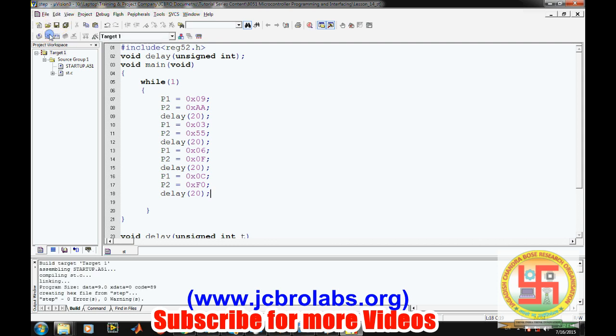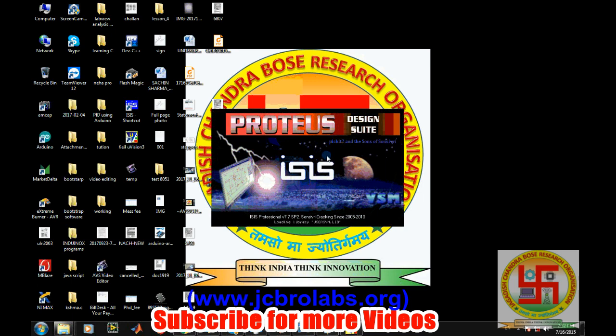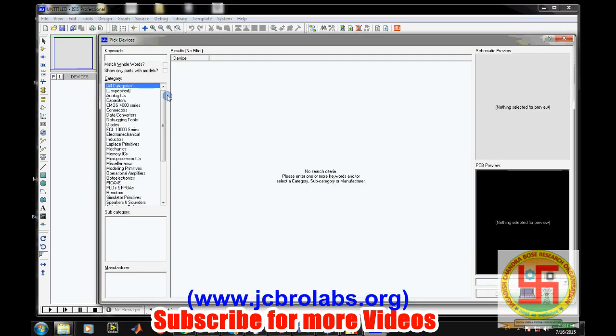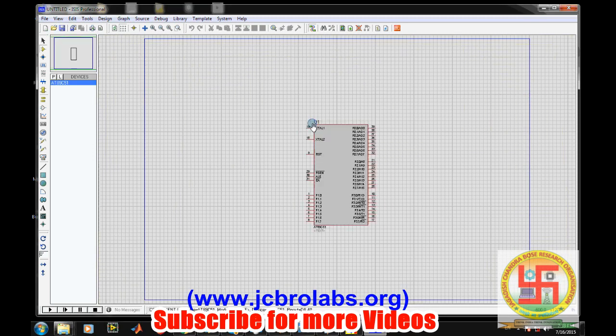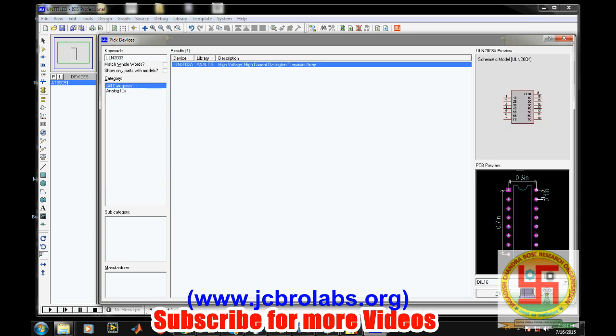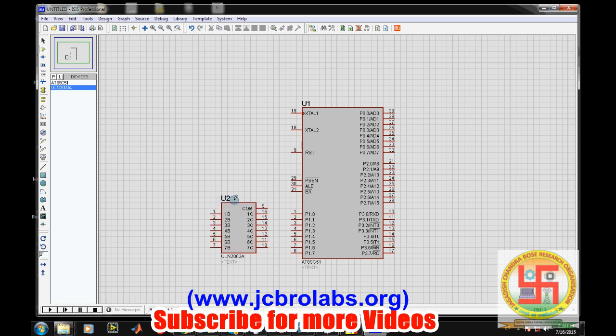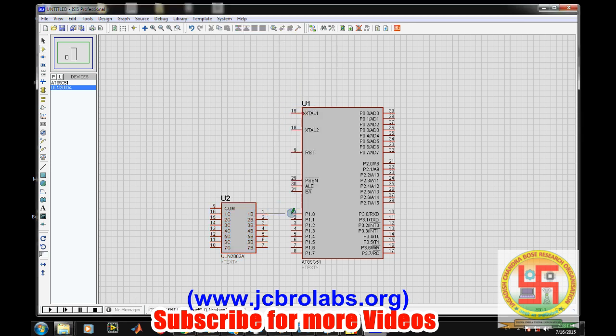Now let's compile it and see. Okay, it's done. Prior to burning this hex file onto the hardware, let's see whether it is running on the simulator or not. So let's take 89C51, and as we have discussed, let's add the ULN2003. Then let's rotate it and make the connections.